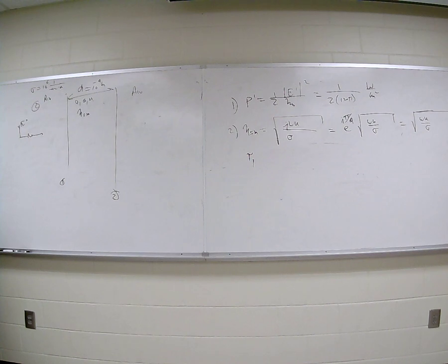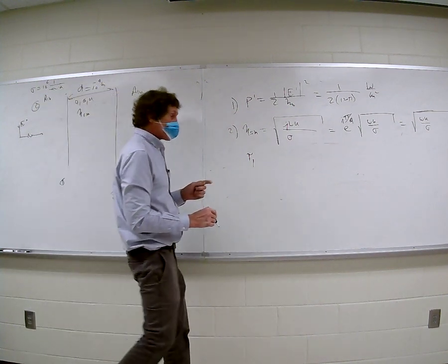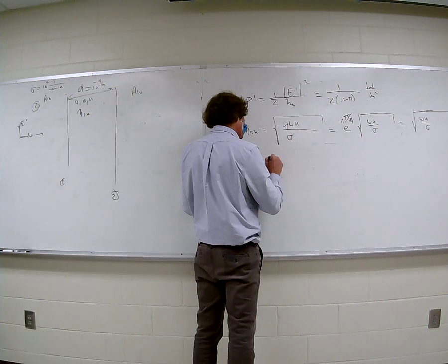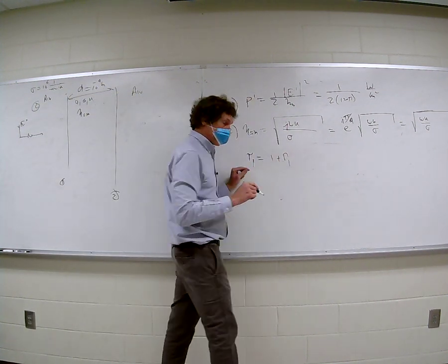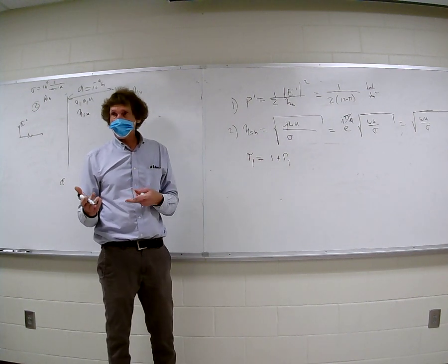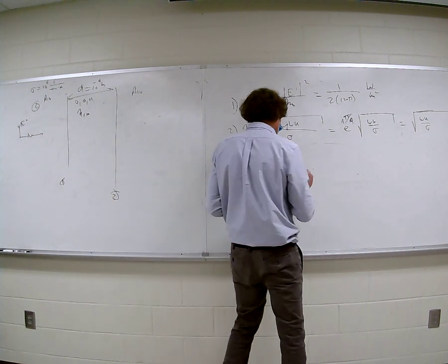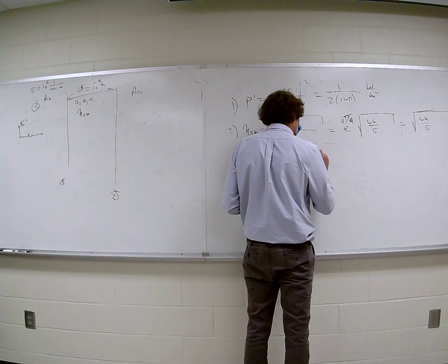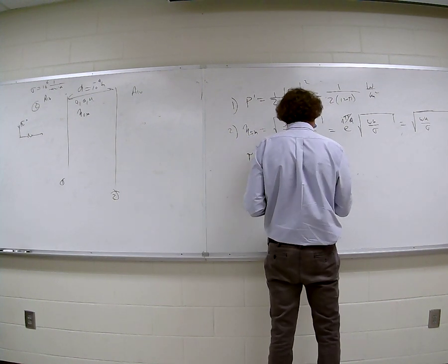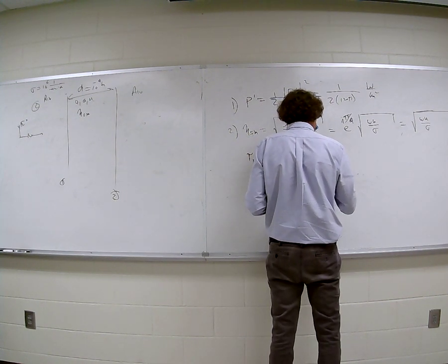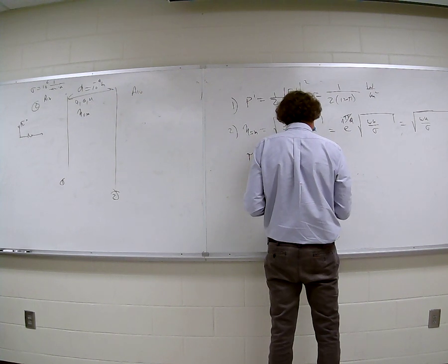And I think it's because of the complex number. I'm not certain, but I think it was that. So, admittedly, you could say 1 plus the reflection coefficient of region 1, but in general, it's easier in my opinion to just do this: 2 times the impedance you're going into, over the sum of the impedances.